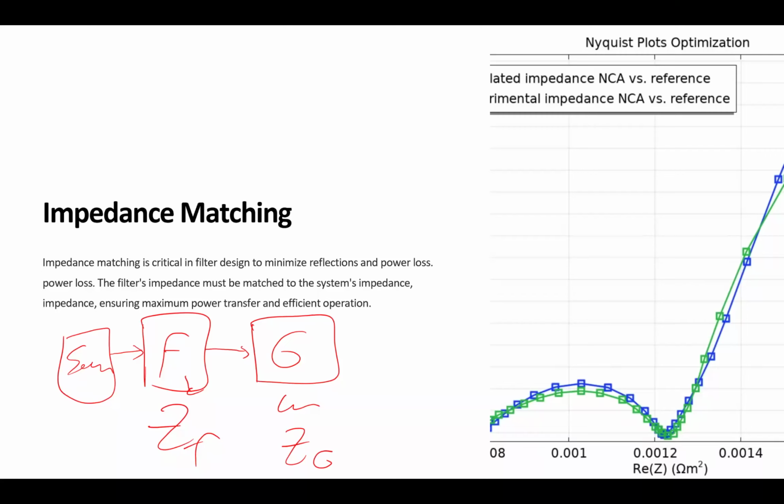Are we good on that? Now, any change in this matching would result in lower power transfer, which is one of the effects of impedance that you have to take into consideration. When you design the impedance, you have to consider what your future load is going to be, so you have to match that impedance. You can't exactly match it because the load is changing, okay? But you have a range, probability-wise. You can say, okay, it's mostly this range, so I'm going to stick to that range.